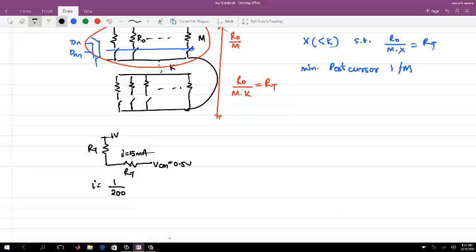If I am using a particular cell, it's like this. Out of the K cells, you choose X cells so that the total impedance is equal to your termination, depending on process variation. That you ensure. Then, out of each cell, whatever ratio of equalization you want to implement, out of M I divide, so M is now main plus post.